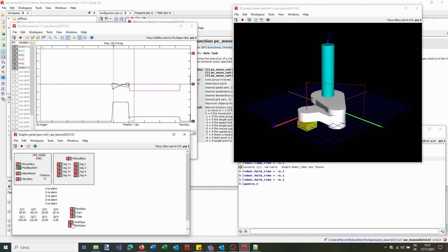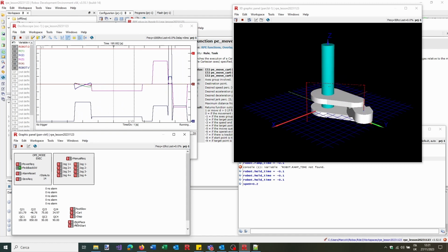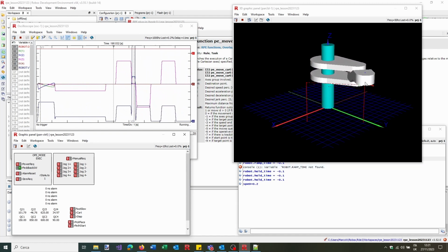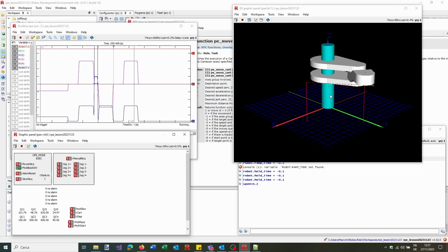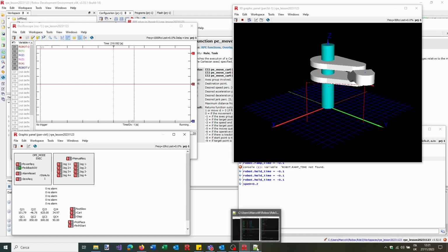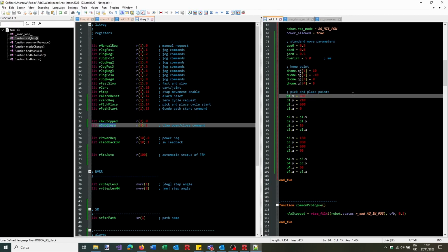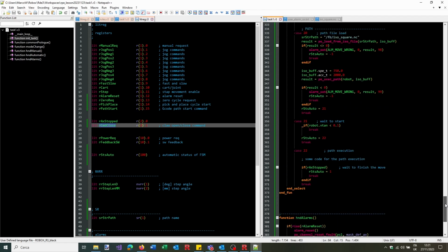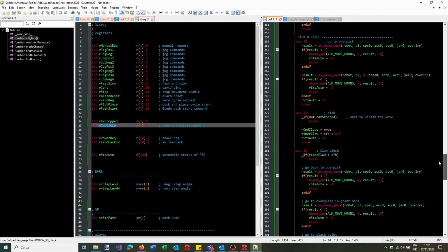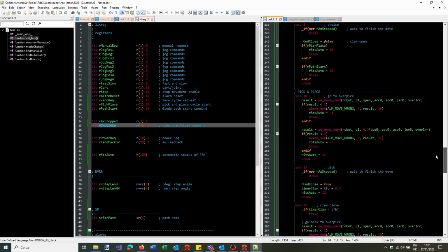Here it is better to move joint. Here, here, here. And we see that the joint movement is very, very fast. So now this is something more that we could improve. But together with this, let's also, okay, let's just say while we go to P1, which is at the end, no, sorry, it's move number 10, that's not Cartesian, that's joint.